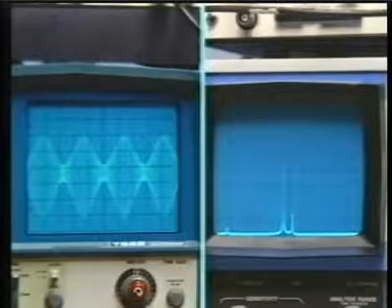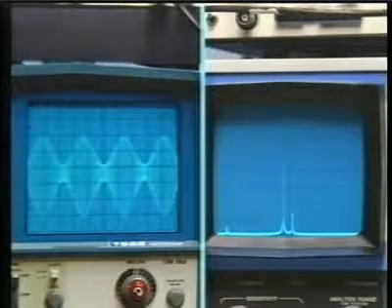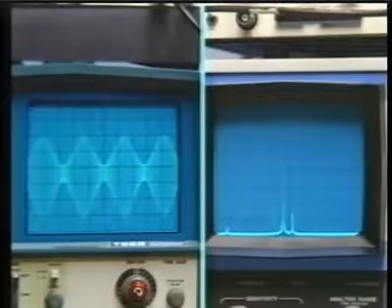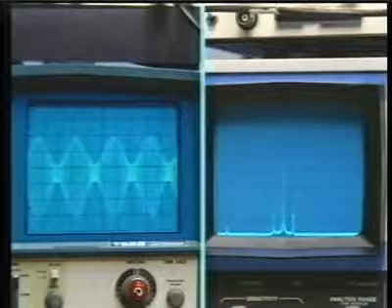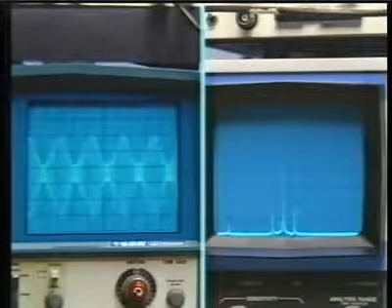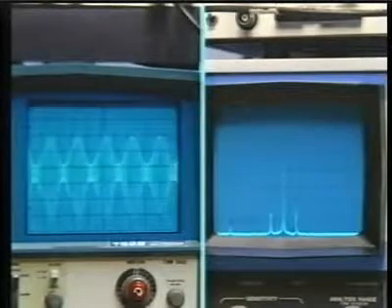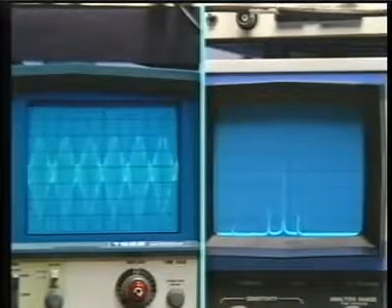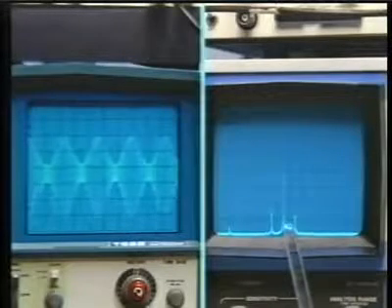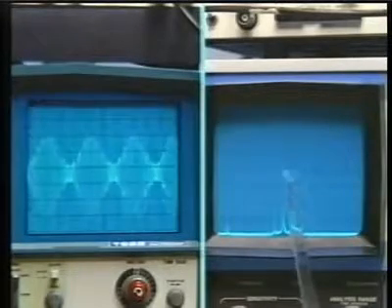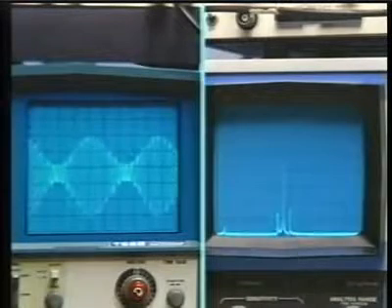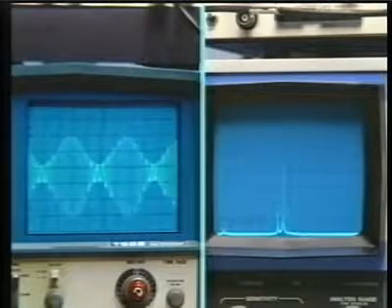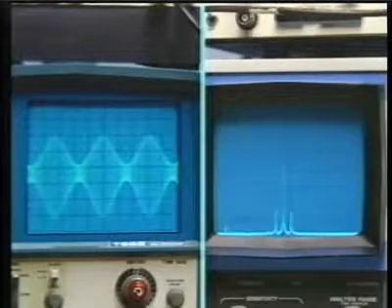Going back to the simplest, the sinusoidal carrier, another thing we can do is to vary the frequency of the sinusoidal signal that's modulating it. I'll make it higher, and you'll notice that the sidebands wander away from the carrier signal in the spectrum. The carrier signal, that is, doesn't have a frequency that's changing as I do this. It's just the width of the band due to the modulating signal. So this is the carrier, and these are the sidebands. That's right. And as we go out very far, those sidebands get gobbled up by the carrier itself. I'll come back to a nice, reasonable point there.